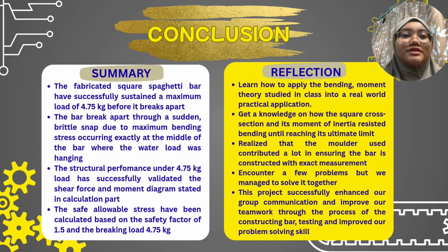So the structural performance under the 4.75 kg load has successfully validated the shear force and moment diagram stated in the calculation part. The safe allowable stress has been calculated based on the safety factor of 1.5 and the breaking load of 4.75 kg. For the reflection, we learned how to apply the bending moment theory studied in class into a real-world practical application.